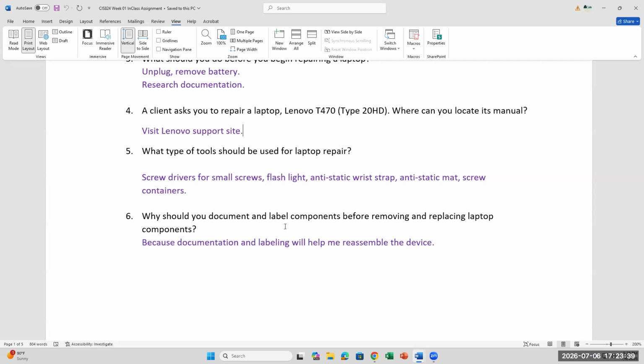So before you work on the computer, when you open up components, before you start touching the components, you need to touch something metal. What that does is it grounds you. On a floor like this, it's grounded. Typically with tiles, everything is good. It doesn't create too much static electricity. Now a kit like this would have a lot of different tools that you can use for computer repair.